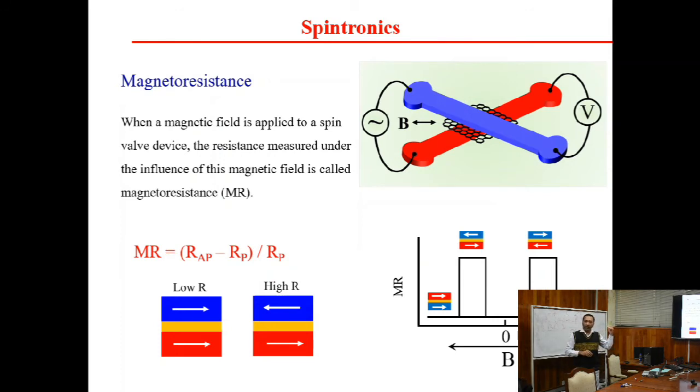When we apply the magnetic field, what will happen? These charge carriers will be aligned, polarized on the bottom side and aligned on the top side. When the switching of these charge carriers is opposite to each other, meaning the orientation of the spin is opposite, you will have the junction resistance at a higher level.